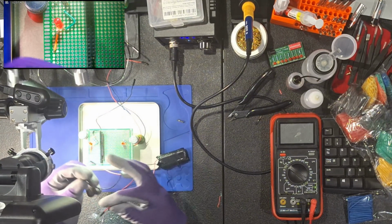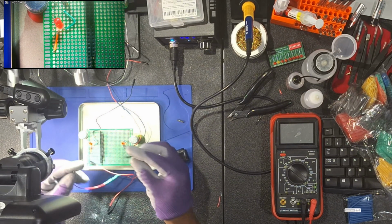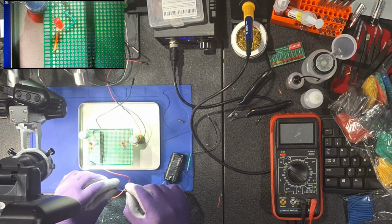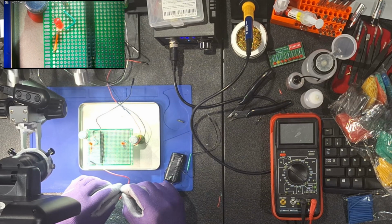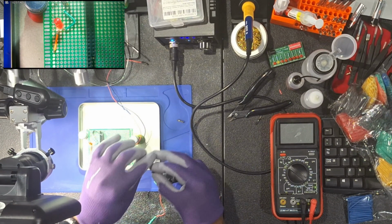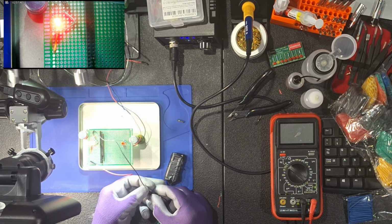I have two AAs that I use to make a battery pack, so I'm getting 3 volts from this battery pack that I made. The LED needs 2 volts or 2.2 volts, so the battery pack with 3 volts should be sufficient without damaging the LED. So connecting the LED to the battery here, it lights up, looking good.